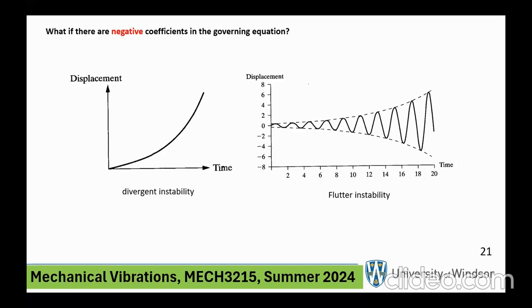And I told you that the oscillations of the deck grew bigger and bigger and bigger, etc. You might say, okay, well, isn't that flutter instability? Haven't we already seen that? The problem is that in that particular video that I showed you, there was a forced vibration. What we're talking about here is free vibration.